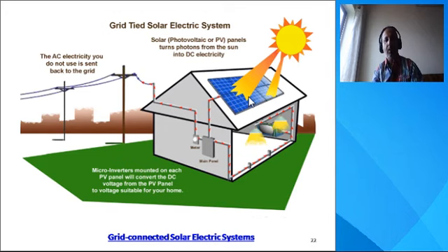In this type of solar array, micro inverters are placed together with the array. Those micro inverters convert the DC into high voltage AC, which is suitable for connecting supply directly to the grid. And one control panel is there with the help of which the supply to the home or the organization can be continued. So here both purposes are fulfilled. Supply is given to the home or the organization, and the remaining extra supply is given to the grid.